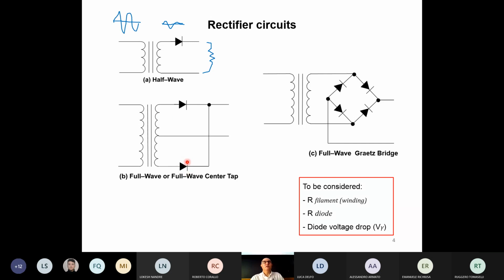They don't cost much because we are using semiconductor diodes, junction diodes. But you have to consider that in the past, each diode of this was an electronic tube, a valve. So something which was very expensive. That is the reason why maybe this was not very popular. Most of the time people used the half-wave rectifier in the past.